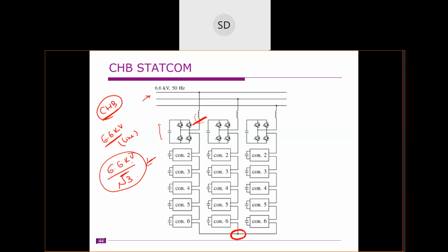Right. So this can be designed in 2 different ways. One is, first we'll select the DC bus voltage, or DC voltage of each source. That means we'll select this one first. Based on that, we will select the number of H bridges that we actually require.